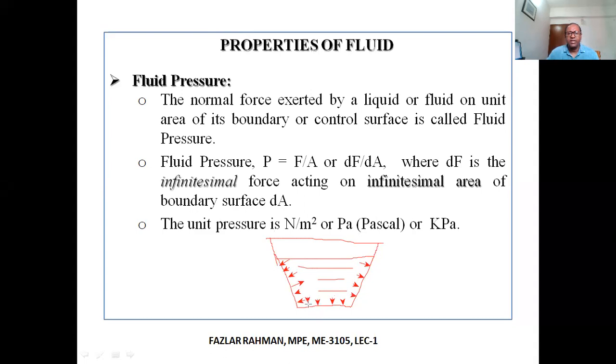Okay, say you buy a plastic bucket, but you thin out the wall, like a polythene bag or a birthday balloon. What will happen? You put water in, it will expand, right? Because the wall doesn't have the resistance to carry this pressure load. So what is the pressure? Pressure equals force divided by area. So if you know the pressure, you can figure out how much force is in the fluid. Say the bottom of your bucket, what kind of area? Obviously round, circular, right? You know the area. If you know the pressure at the bottom of your bucket, then you can calculate the total force at the bottom of the bucket.